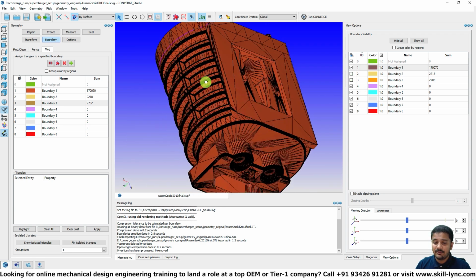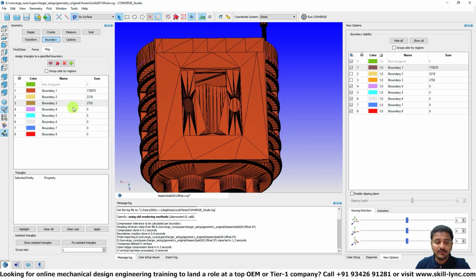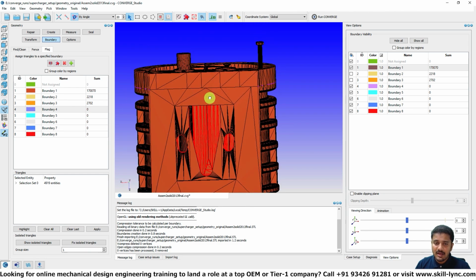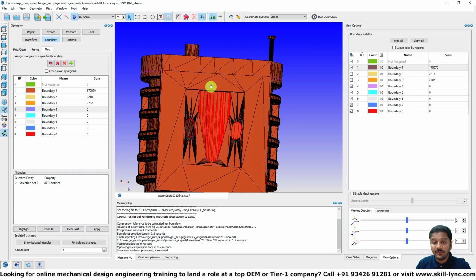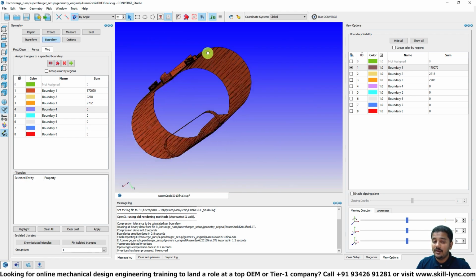Alright, so that looks good. So the next thing that we want to flag is the internal faces. So I'm going to be selecting those guys. I'm going to click on angle method, and I'm able to select this particular portion. And what you can also do is you can do Ctrl+L shortcut key to kind of isolate the selection that you just now made, right?